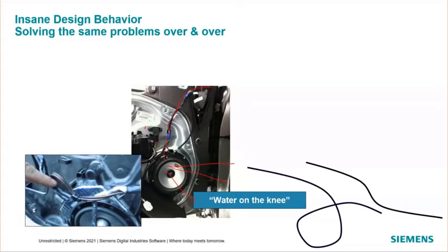As she looked at that wire harness, she noticed that in the prior version of the harness, there was a wire loop in it. And of course, you know what that wire loop was doing. It's performing the function of keeping the passengers dry, by carrying the water away from the speaker.